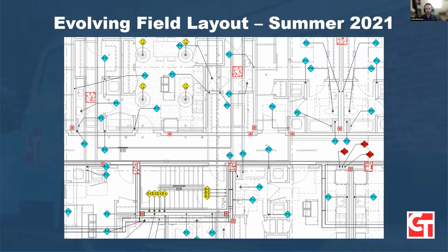Between just the speed that the concrete contractor works at, and also the fact that this was a post-tension podium project, so lots of very critical structural components embedded in the slab beyond just your standard steel reinforcement, it really required that we were able to lay out sleeves accurately and quickly enough as to not slow them down. So we partnered with them and started really adding this layout process to our coordination efforts.